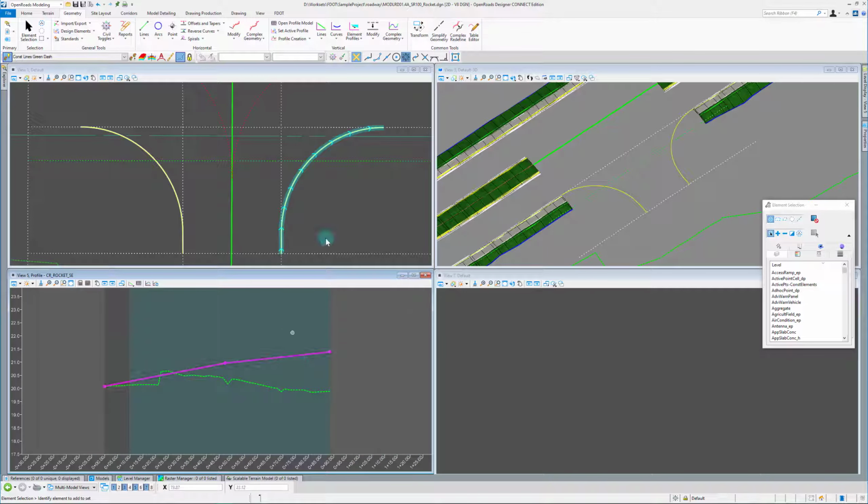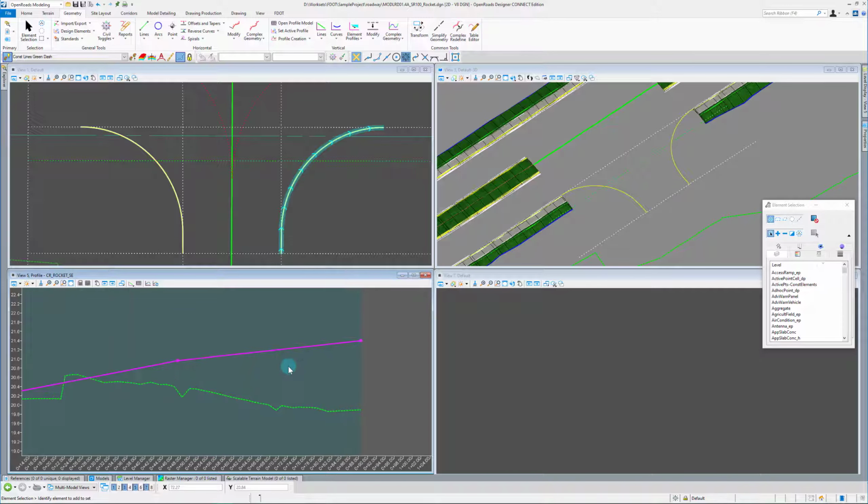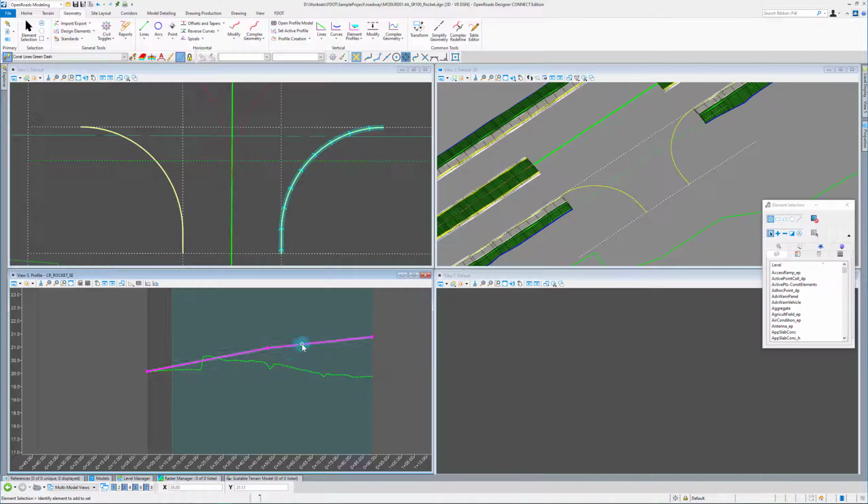So one thing to make sure of when you're doing this is that it's going to end up being a curb return. For curb, we need to make sure that we have a 0.3% cross slope at a minimum. So I just want to make sure that this cross slope and this slope are 0.3. On this particular side street, it doesn't seem like we're having any issue. Looks like our road here is a good deal higher than the existing that we're tying into, so we have a pretty decent slope that we're tying down into.